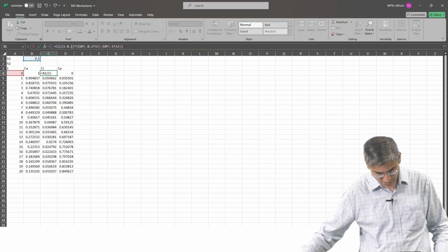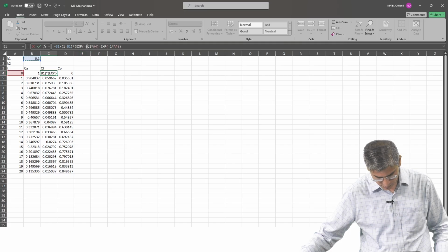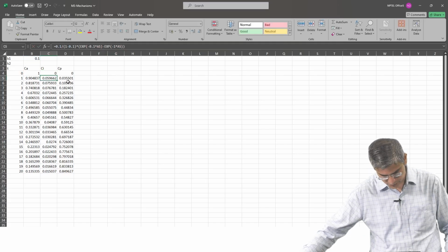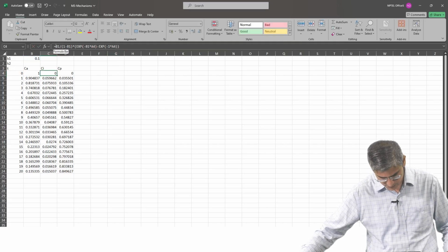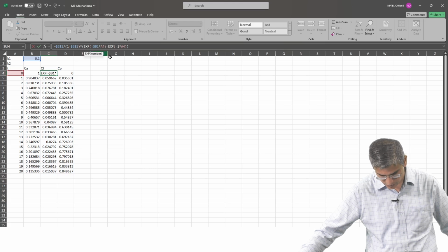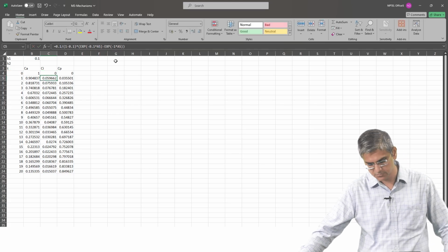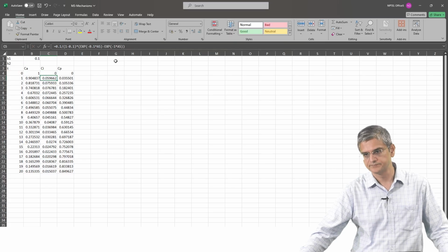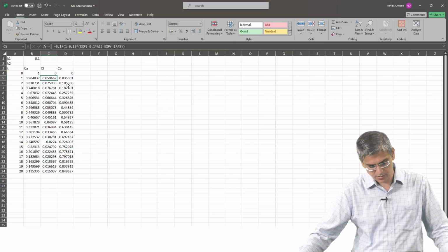I will put this guy and this, 3 places I think, and again I will just put dollars. Wherever B1 was, I am replacing that with $B$1.